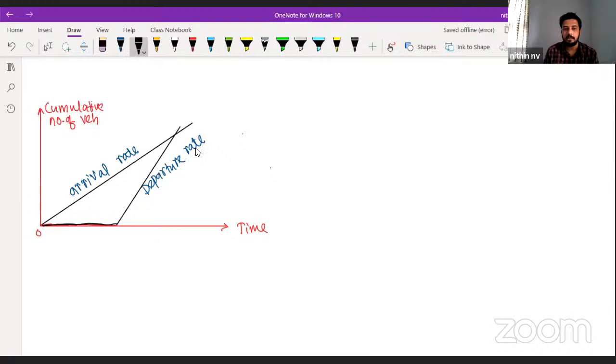Okay. So throughout this red signal, till the green signal, vehicles will be under queue. They are not departing anything. We are just drawing the departure rate. So whenever this red signal is finished and the green signal is starting, then what will happen? Then the vehicle will start departing. Understood? So it keeps on increasing. Is it clear? So after green, we will be having some amber also.